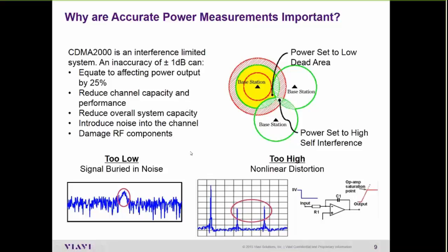And so again, if you have too low a power, you're going to have low signal. It may even be buried in the noise. And if you crank this thing up too high, here we've got an example of plus or minus 1 dB. But if you really crank the power up, and I've seen this in areas where people used to just change out radios, they'd just pull out one and plug another one in, and they wouldn't bother to set the power. And maybe the radio was already programmed to output power at, say, 50 dBm, so it was way overdriving the amplifiers.